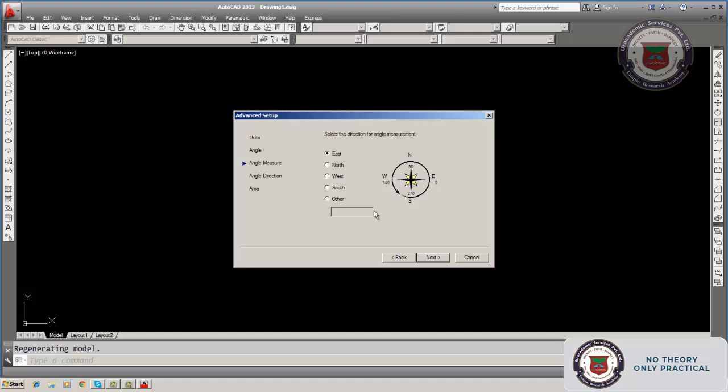And here the measurement of the angle. How you want to measure angle? See here he has shown the arrow. It measures from east to north, west. And suppose you want measurement from north, then it comes from north measurement. It will be 0 here and it measures 90 like that. If it is east, it is 0 in the east horizontal direction, and from there you reckon 0, 10, 15, 90 like that. North means 0 will be calculated from vertical direction and measures like that.